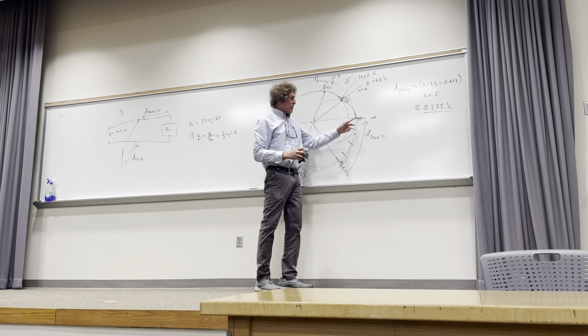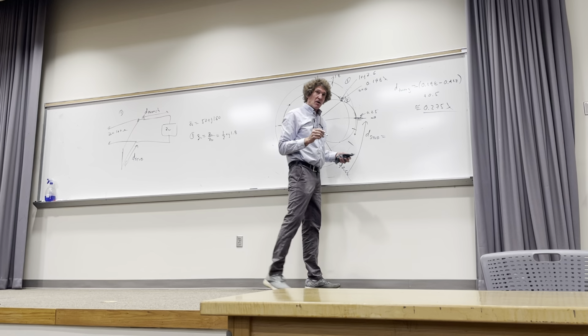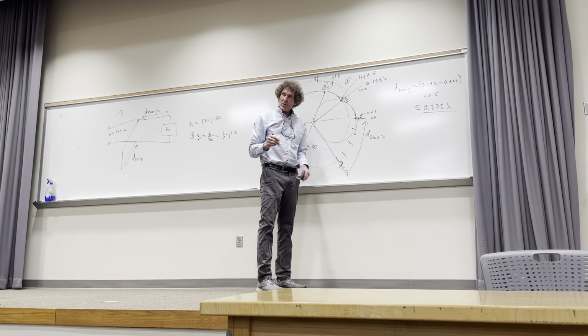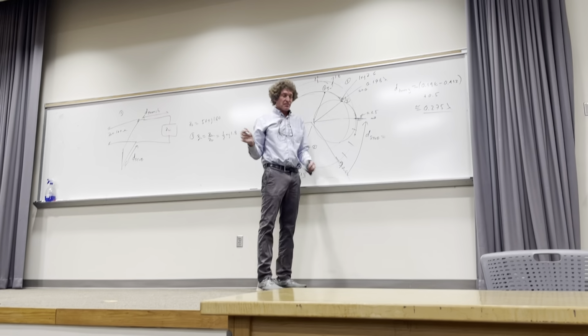Now, this point right here is 0.25 lambda on wavelengths towards generator. This point, if you eyeball it, I want to say it's 0.31, approximately, maybe just slightly less than that. Can you all see it on your Smith chart? Make sure you can locate that point. Regardless if you got it right, make sure you know how to do this one.